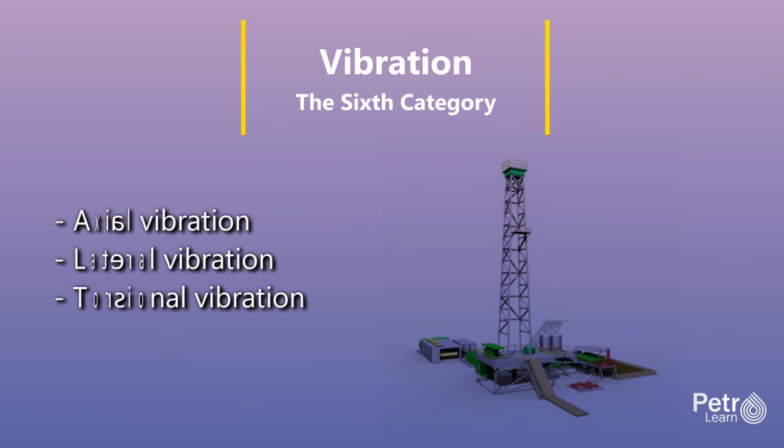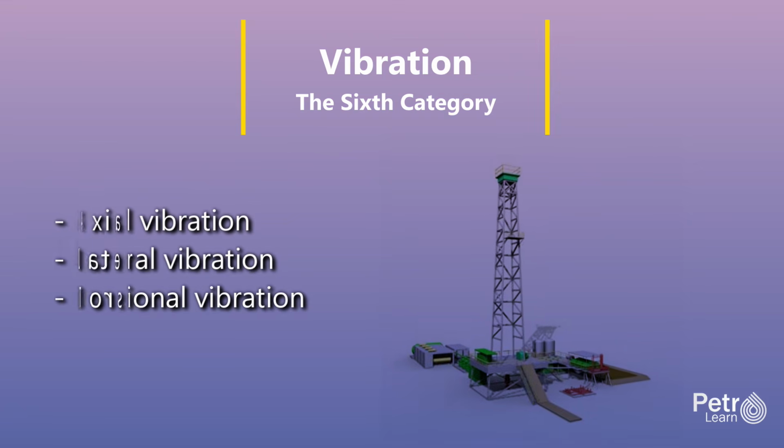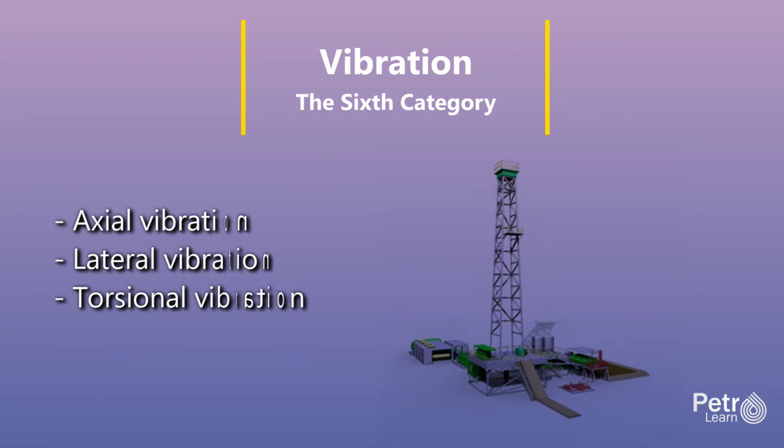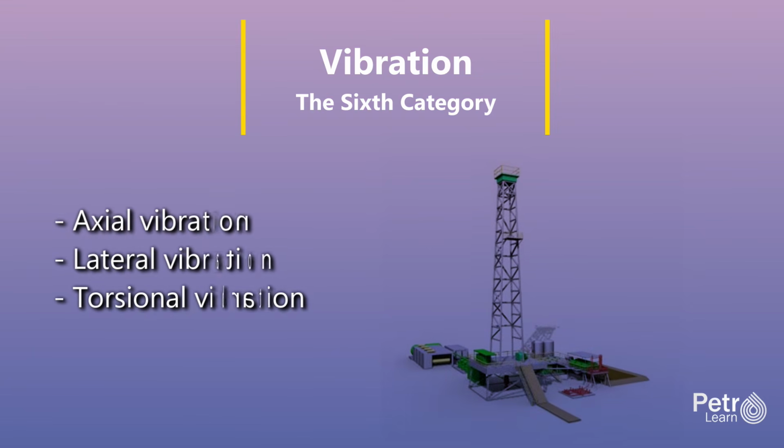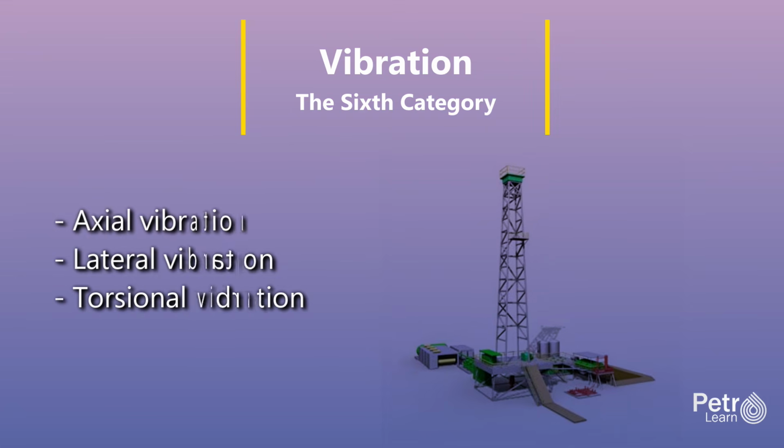Lateral vibration, or whirl, occurs when the bottom hole assembly bends and the drill collars contact the wellbore wall, causing the assembly to rotate around the hole eccentrically rather than about its own axis. Torsional vibration, or stick slip, is particularly damaging.